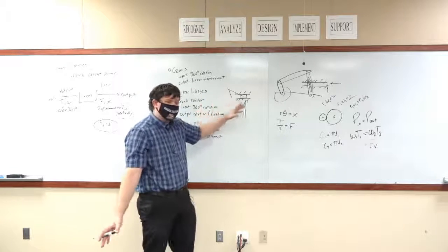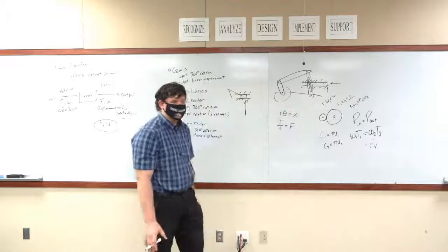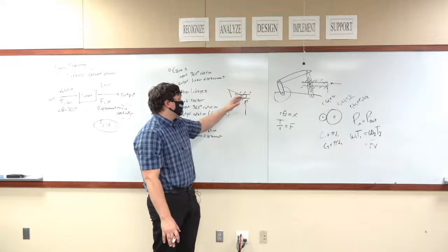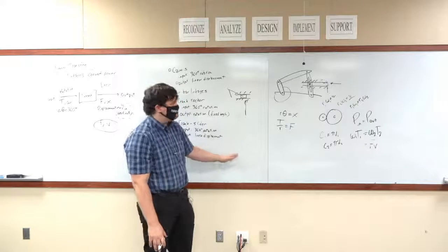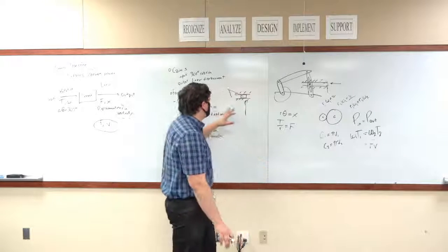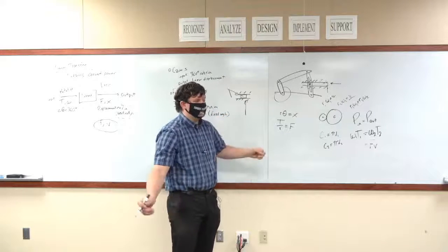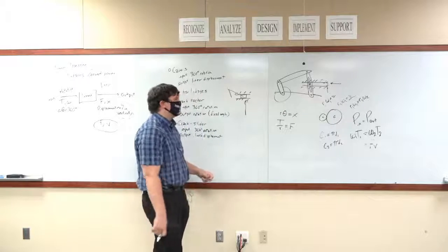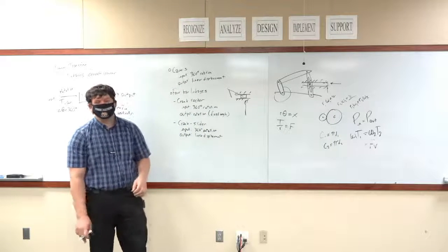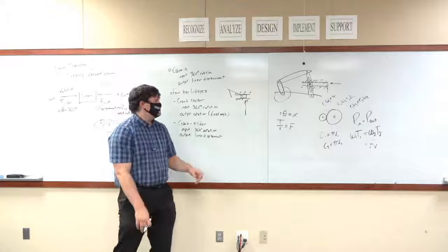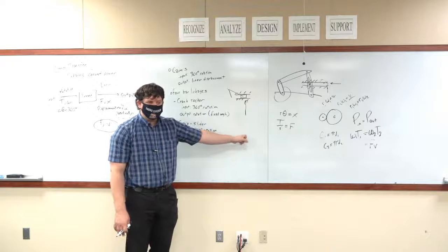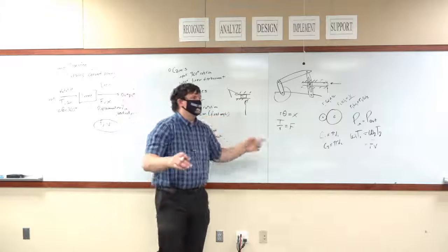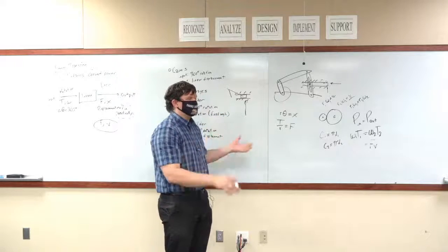So that's kind of the difference between these two types of systems. Yes, this is also a 4-bar linkage, and yes, this has great application. But if you want to prevent force transmission from being carried back directly to your motor, maximizing your power output, it's best to make it so that the direction of the force that's going to be applied doesn't go like this.